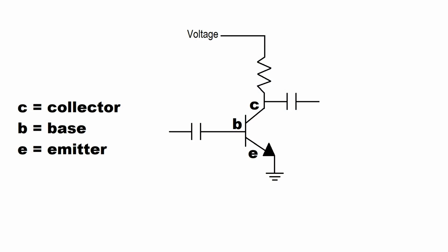Restricting the flow of current can also be useful in controlling the amount of current going to a circuit. In a simple transistor circuit, like a fuzz pedal, a resistor may be needed between the collector and the power supply to ensure the transistor is getting the optimal amount of current for the application. Because transistors are so mass-produced, there can be some variation between the qualities of the transistors even if they are the same model from the same manufacturer. This is especially true with germanium transistors.